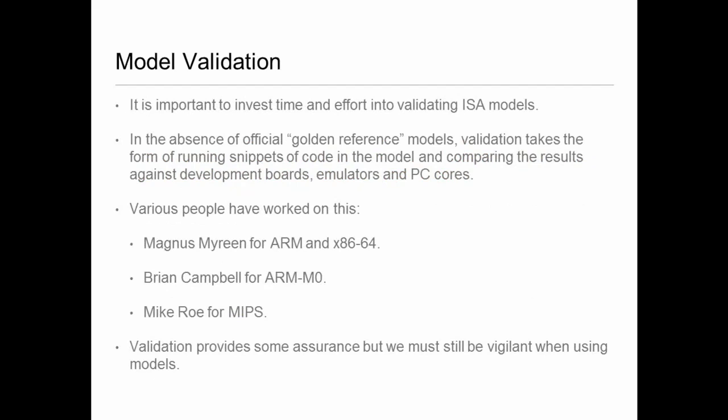Having done these specifications, it's very important to actually try them out and make sure that they are what they're supposed to be. You don't have these sort of golden references we can compare our models against, so our approach has generally been to use development boards, emulators, your local PC, and just do a comparison for as many instructions as we possibly can.